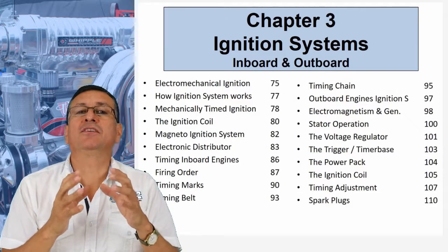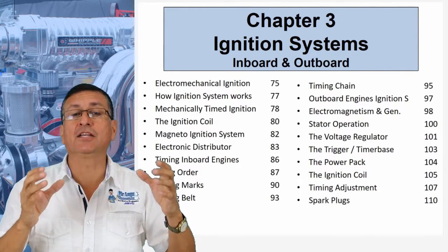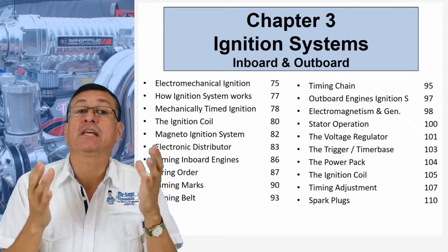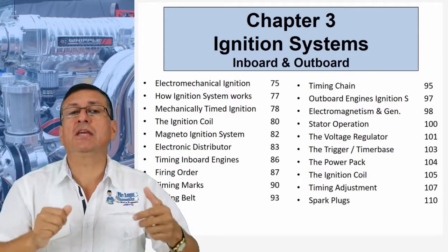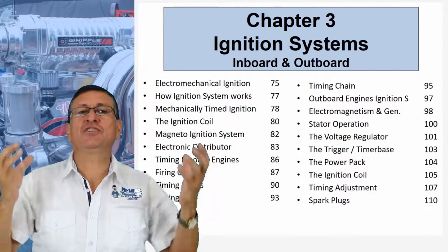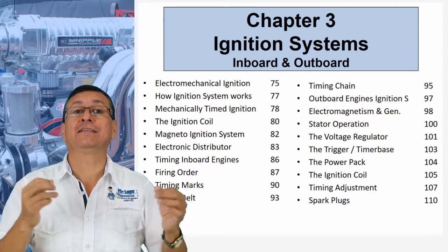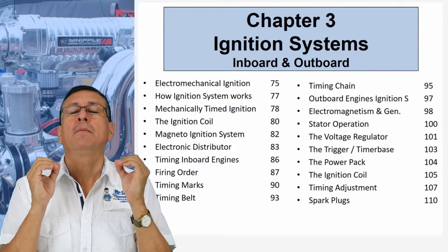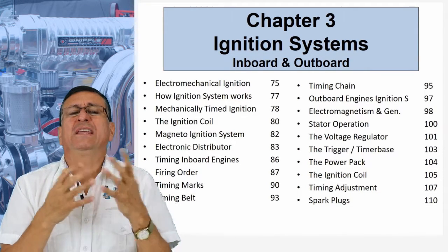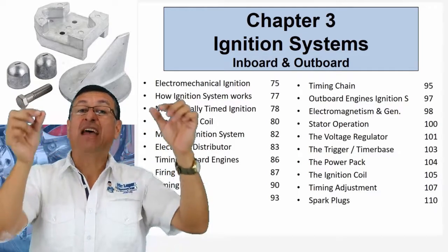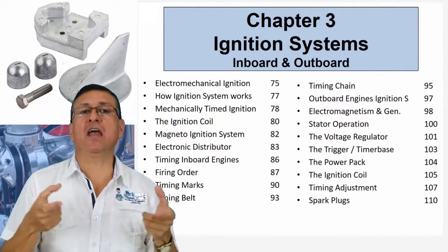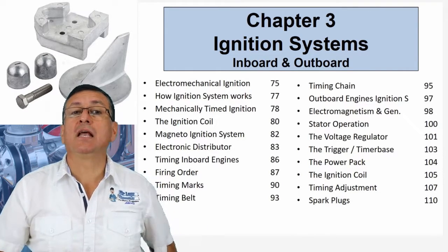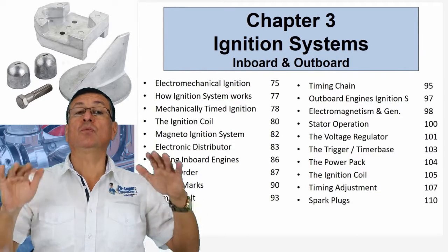Alright, this is the situation in between the computer and the spark plug. But another important thing is the protection of the harness, because in those engines the injection system depends on the computer and the signals. For that reason, the ground is critical. The ground should be a good ground. What is the ground? The ground is the connection of the harness with the block of the engine, and the block of the engine properly connected with the sinks located in the lower unit, in contact with the water.